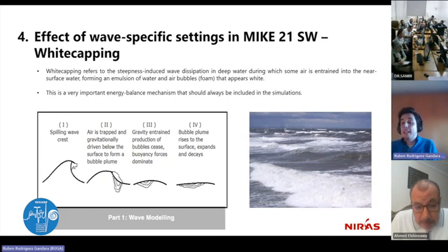But the thing is that the mechanism is not the same. It's not due to shoaling. It's not due to the seabed. It's just due to the fact that they are growing so big that their steepness is getting smaller. The ratio is getting smaller, and then it's the mere weight of the wave which causes them to collapse.